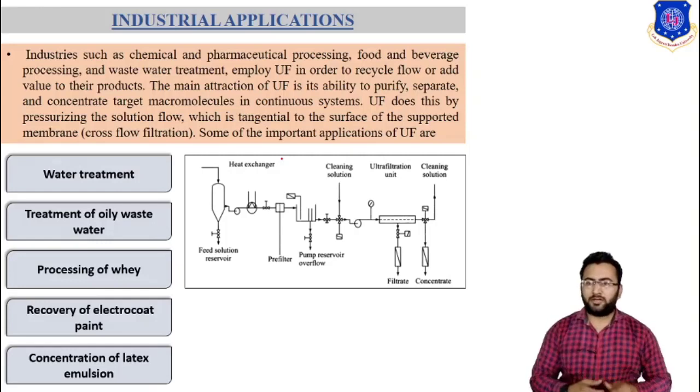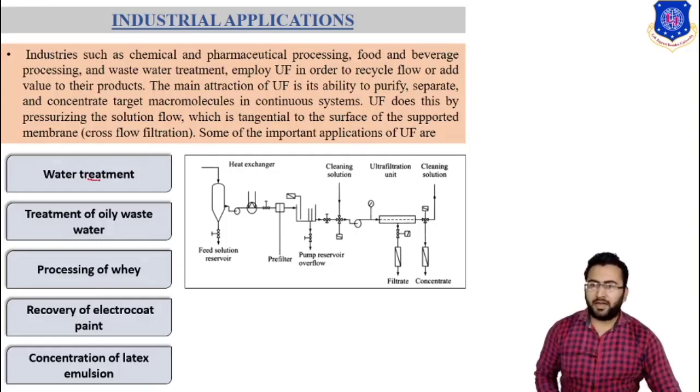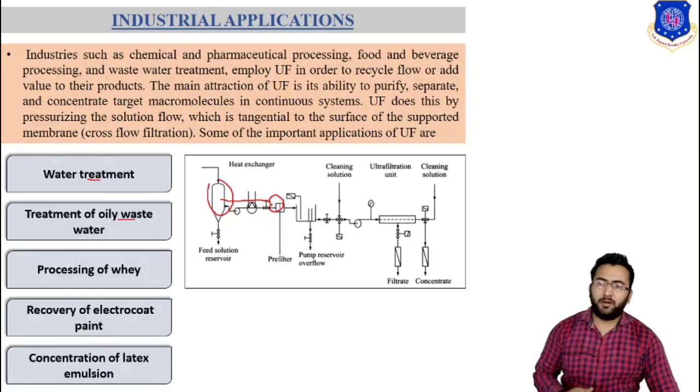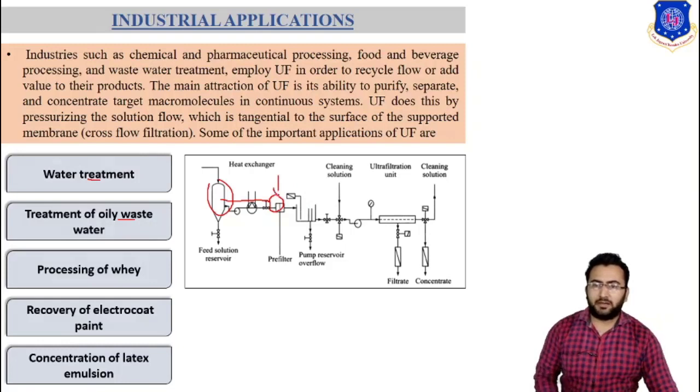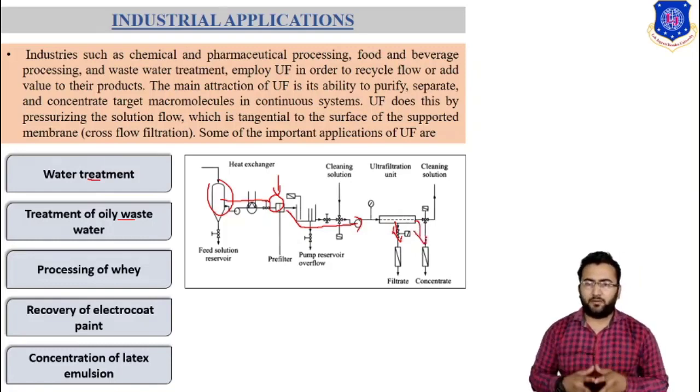For treatment of wastewater and oily wastewater, first we require a storage tank, then it passes through the pre-filter, where solid particles are removed, and then it passes through the ultrafiltration unit, then goes to secondary or tertiary treatment, where we can get pure water.